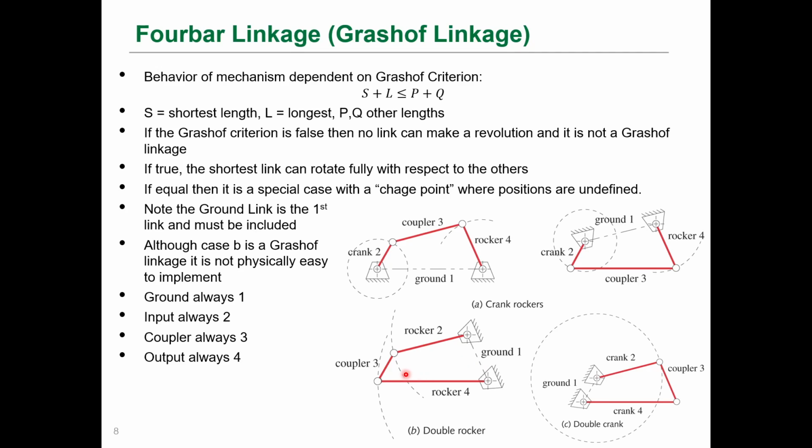In this case here, the shortest link is actually this coupler. And although if you rotated, this coupler would spin around, you can't actually physically realize that motion usually. I mean, it's very difficult to implement in real life. Okay.